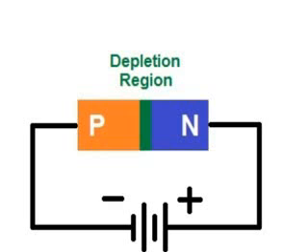This doesn't mean that the N region now has holes in it. It means that the electron-rich N region has no more spare electrons in that area, so it becomes neutrally charged. This now has been turned back into an insulator. The area at the PN junction where the N region electrons have gone away is called a depletion region. It's an insulator, and no current can flow across it. This is why a reverse bias diode won't flow any current.